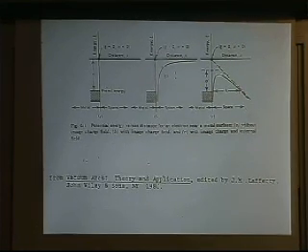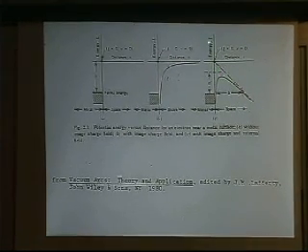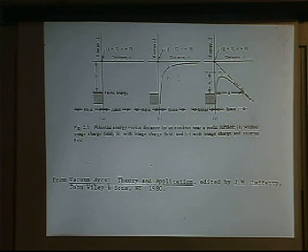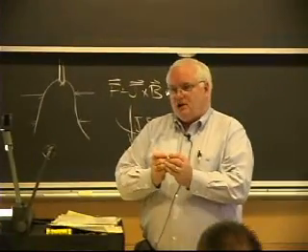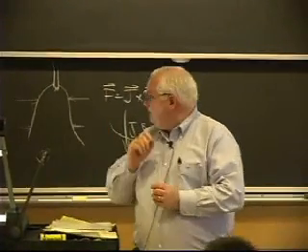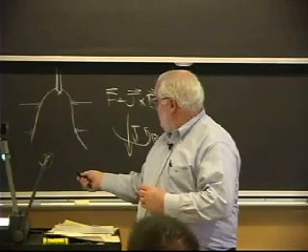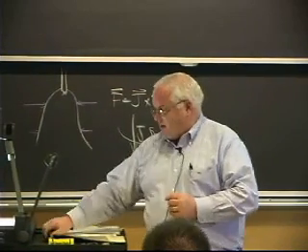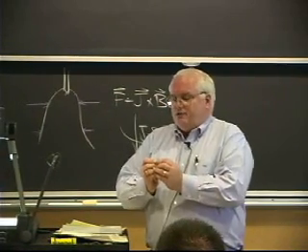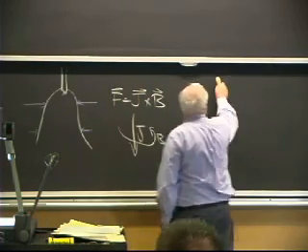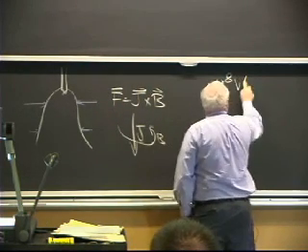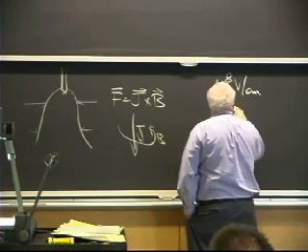Well, it turns out Paschen breakdown, well, let me back up. It takes something on the order of 10 to the 8th volts per centimeter, 100 million volts per centimeter. So if that's a centimeter, it takes 100 million volts to essentially strip the electrons out of the metal by field emission. Okay, this is called field emission because you've got an electric field helping pull the electrons out of the cathode. Well, if I get down to something on the order of 1/10 of a millimeter, so I need 10 to the 8th volts per centimeter, and if I get down to